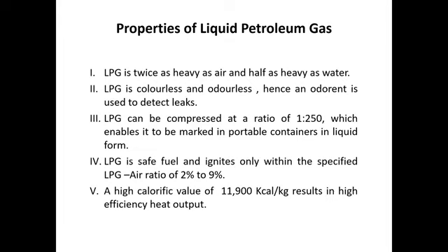It can be compressed at a ratio of 1:250, which enables it to be marketed in portable containers in liquid form. It is a safe fuel and ignites only when the LPG-air ratio becomes 2 to 9%. It has a high calorific value, that is 11,900 kilocalorie per kg, which results in high-efficiency heat output.